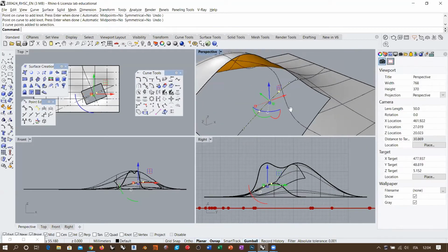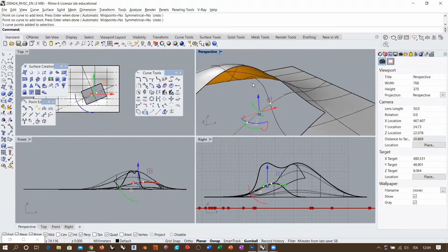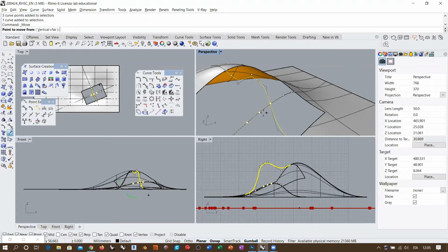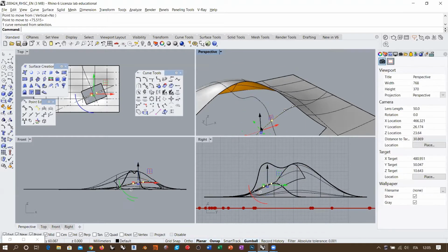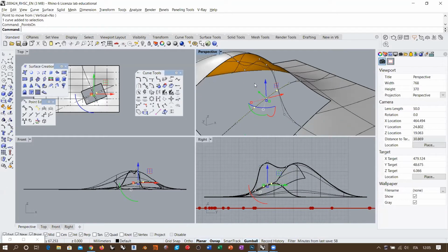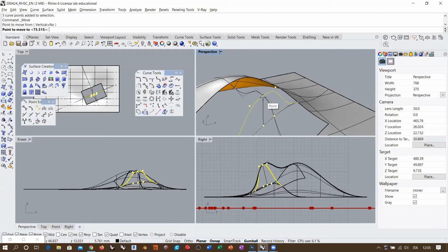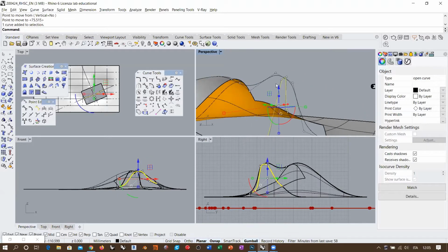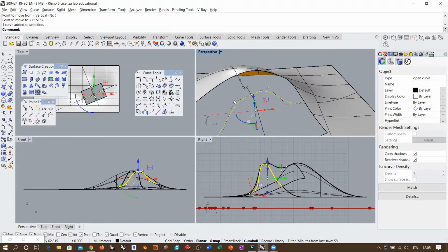And I can take these 3 points, and I must bring them, as we already observed, to be coincident with this center point here. So I would simply move this point here. Sorry, I need to show the control point. Yeah, okay, or else they are going to disappear. Okay, so I'm going to take this control point and move them so that this point is coincident with this point here. These 3 points are not necessarily aligned. I mean, this, and this.